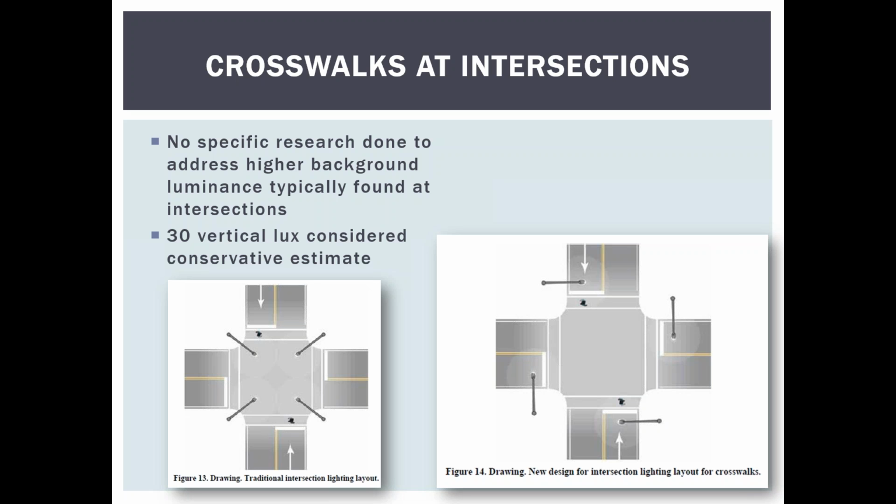And I know that the standard design from when I had left is now to put 2 lights per corner. In some cases, the lights come with a 2-light head, where you're lighting both sides, and strategically placed when possible, so that you're lighting the approach side for the crosswalks. It's not always possible, but when you can do it this way, as opposed to the backlighting, the pedestrian will stand out better.